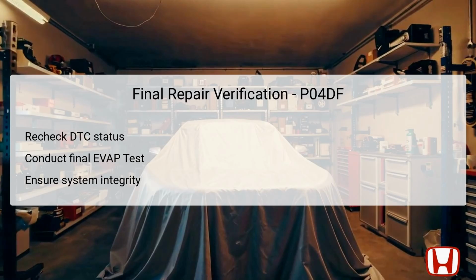After completing the repairs, the final repair verification is vital to ensure that the issue has been effectively resolved. Start by rechecking the status of the DTC P04DF using the HDS. If any DTC is still present, further investigation is required. Next, conduct another EVAP test to confirm the system is functioning correctly without any further issues. The results should ideally show that the system is operating within normal parameters. Evaluate and ensure that all connections are secure and components are correctly installed. This step provides a level of confidence that the repairs made have restored the EVAP system to its original design